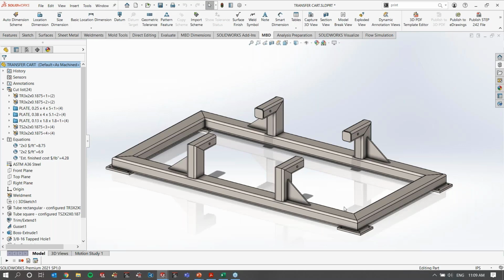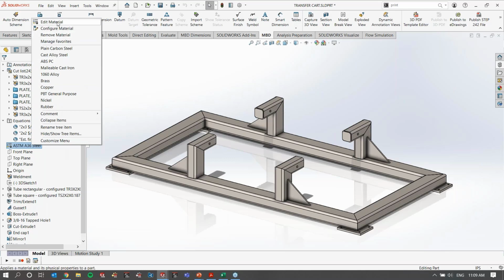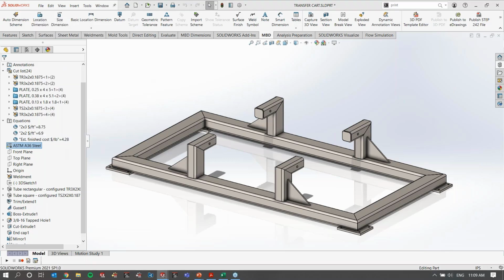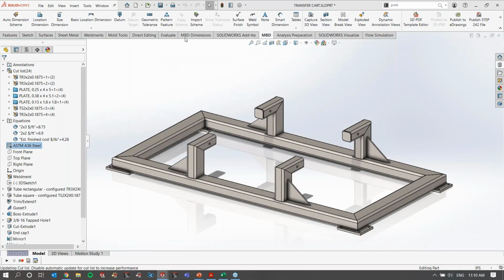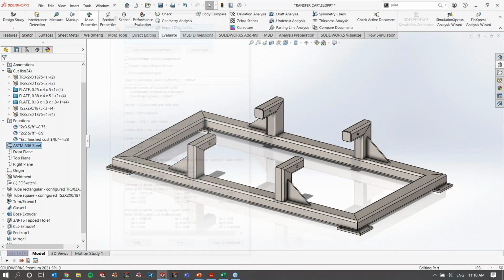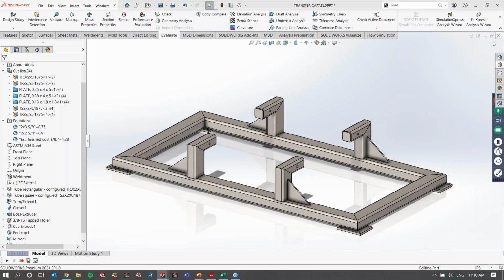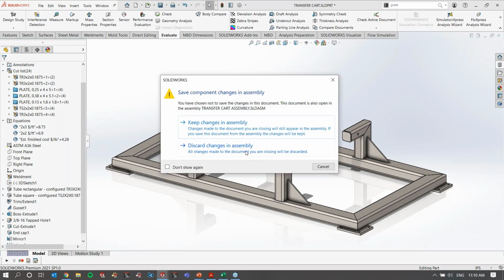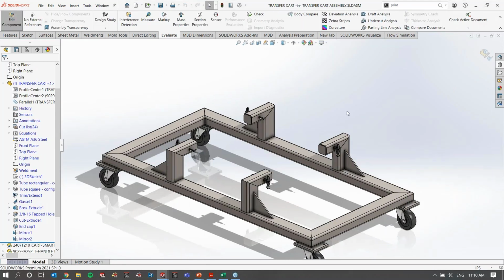And once we are done with that, you can also see that SolidWorks has an inbuilt library of different kinds of materials. Now, all these materials you can actually just add to it, and all the mechanical properties are already there. So any kind of material, once you add, you can actually know the entire mass of this particular body. You can know the mass, you can know the center of mass, which is kind of important when you're talking about designs. So let's just close this. Let's just take a look at a different kind of design right over here. So let me just quickly change.